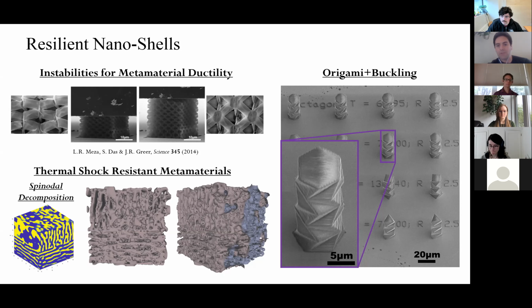materials. So thermal shock being, if I take a really hot thing and I put it into a really cold bath, it'll crack. This is why you want to cool your stuff down slowly coming out of the oven, otherwise the glass will crack. So we're trying to take some fundamental principles of thermal shock resistance and density and lightweight structures, along with structural gradients, and create things that are thermal shock resistant. This one has applications in airplane turbine engines. So the coating for turbine blades in gas turbines, which normally you have a very slow ramp up so you don't crack the coating on the turbine blade.